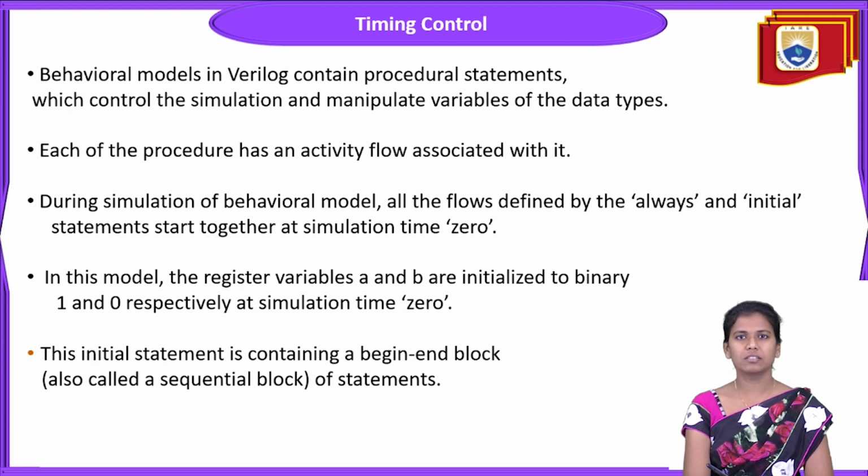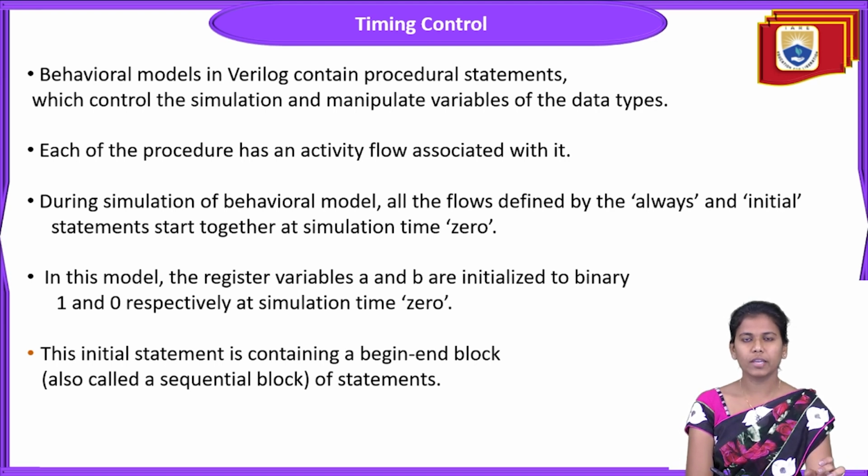In the last class, we had discussed the procedural assignments. Here in the timing control, we also come across the procedural assignments, both the non-blocking and the blocking assignments, and the continuous assignments. So, what is timing control? We all know that in controlling electronic devices, the combinational as well as the sequential circuits follow some delays. With some delays they will produce the output, and not only with the output but we also see some delay constraints with respect to the input.